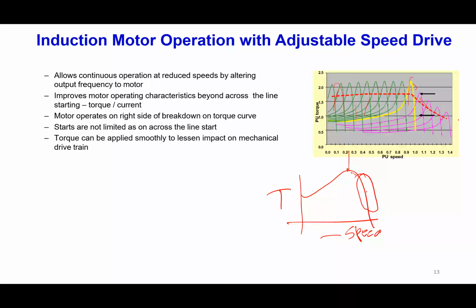They used different techniques like star delta connection, or for a wound field induction motor, rotor side resistance, to reduce the starting current. But with power electronics, we can gradually increase the frequency, and correspondingly the voltage, so we can limit the starting current drawn from the source.